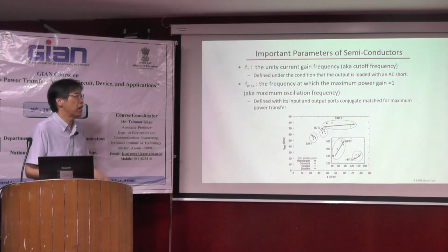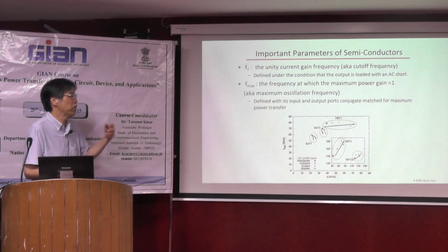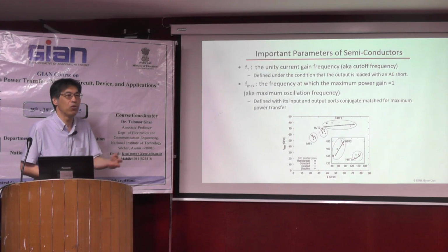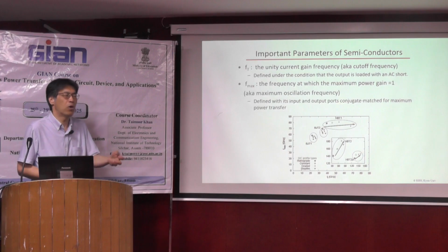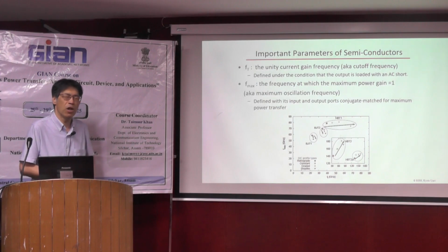And additionally, I will explain at the end of this talk that to increase the efficiency, we have to use higher harmonics to add more power and more efficiency. So if we find, for example, an Fmax of 3 GHz, it seems we can use this semiconductor with an Fmax of 3 GHz in the 2 GHz amplifier.